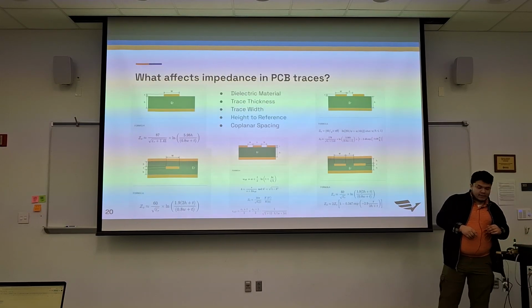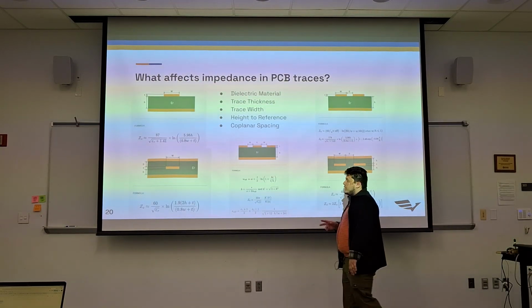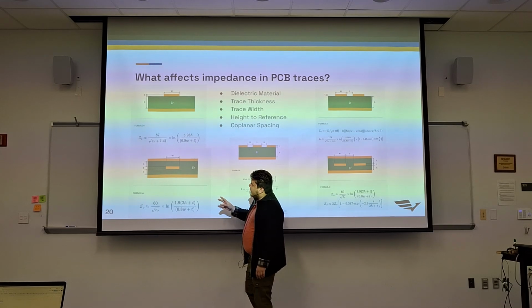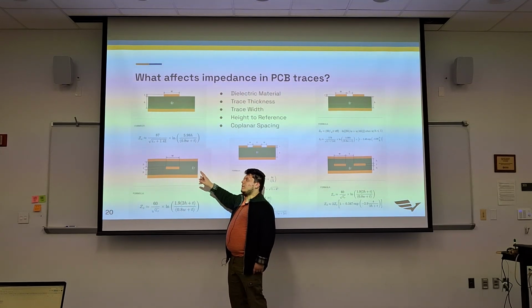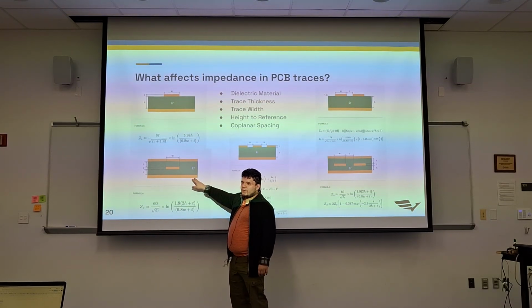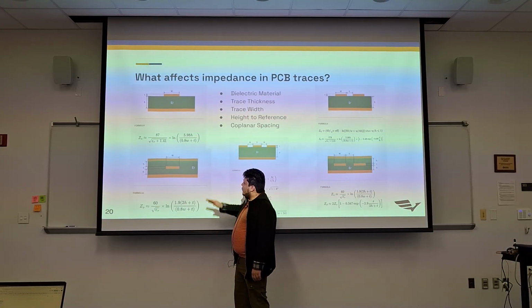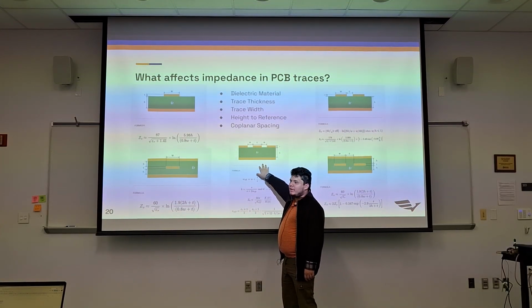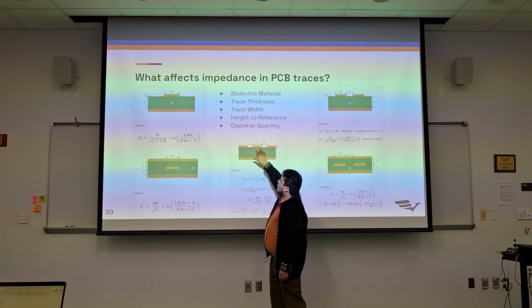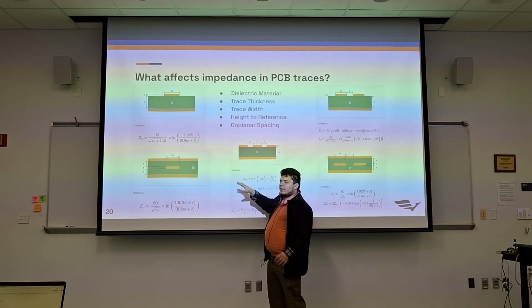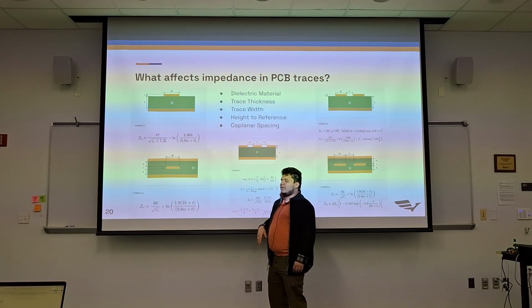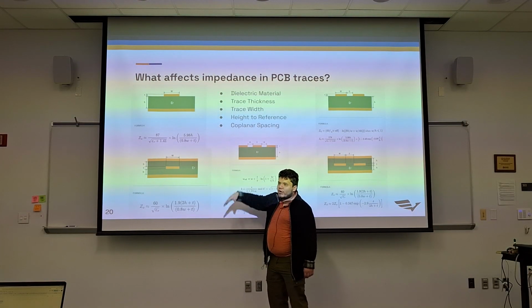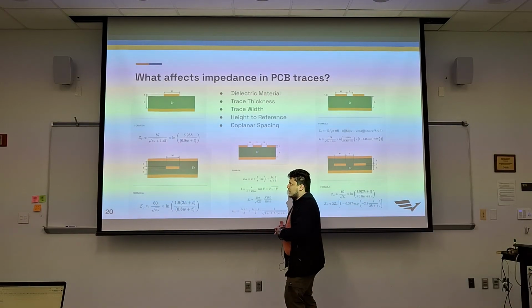This is especially good if you need really high, we're talking megahertz to gigahertz levels of speed and frequency. You need that. Because otherwise you would need this, and we're not touching this, because this is basically that but adding copper on the sides. And for that you need a bunch of shielding vias, and you also need to remove the solder mask, and there's more processing to it.